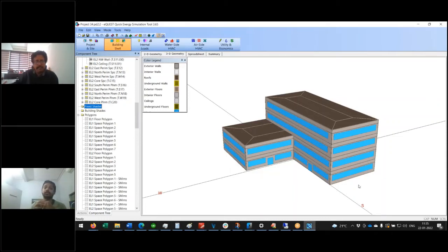You might know that in the base case, you have to rotate the building 4 times. So if you create fixed shades, the shades will not rotate. The shades will stay where they are. They will not rotate with the building. So always go for creating building shades.